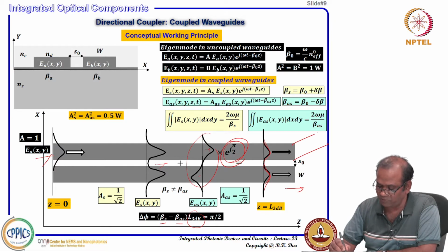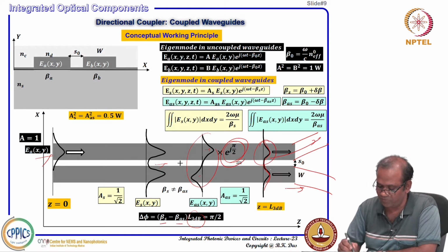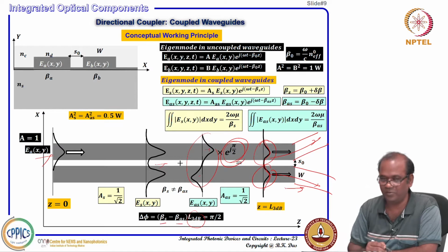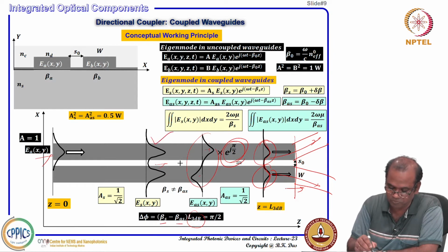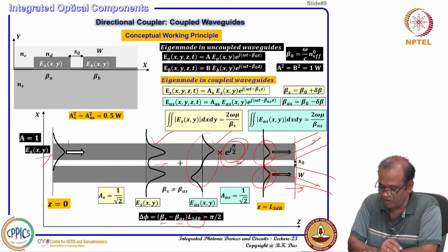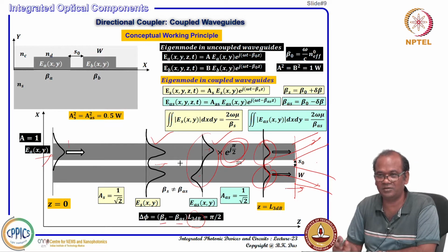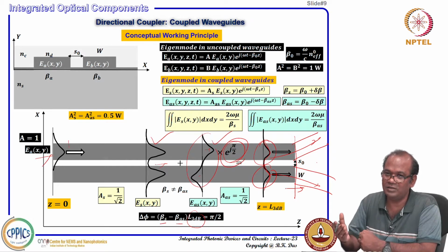And at this point, if you separate or decouple, then this fraction will lead to this waveguide and this fraction will lead to this waveguide. Suddenly you are breaking the orthogonality condition here. The orthogonality condition for the symmetric and asymmetric supermodes starts here at z equal to 0. As long as you maintain the coupled waveguide cross section, they will travel like orthogonal modes.